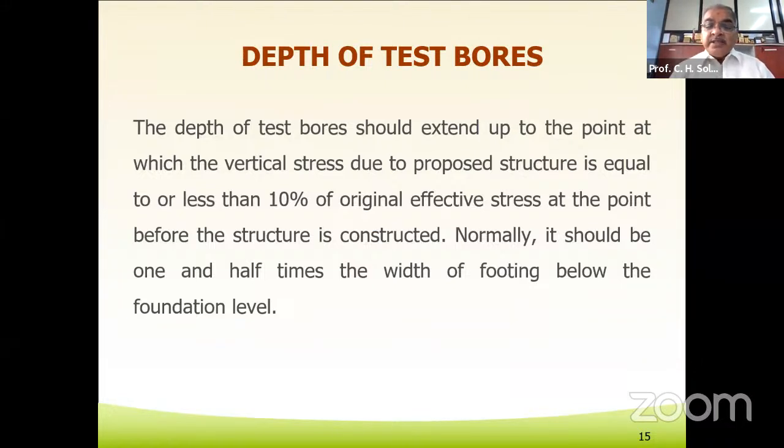The depth of the test bore should extend up to a point at which the vertical stress due to the proposed structure is equal to or less than 10% of the original effective stress at that point before the structure is constructed. Normally, it should be 1.5 times the width of the footing below the foundations.